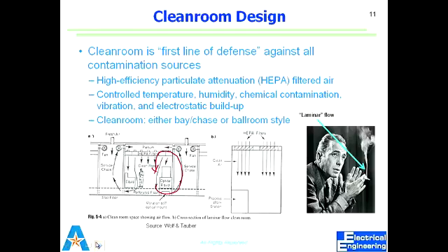Charge buildup, again: when you are doing your processes, the wafer has to have controlled charge. We do bias our wafers during many processes because we want the reaction to happen fast enough. If we have a positive species that we want to react on the surface, we may bias the substrate to negative. So we don't want uncontrolled charge buildup as well.